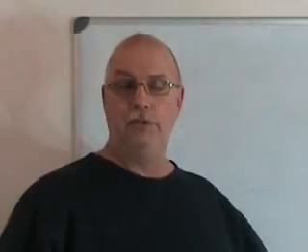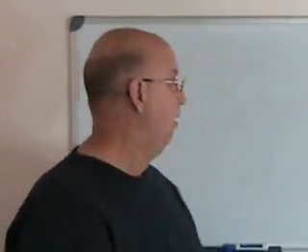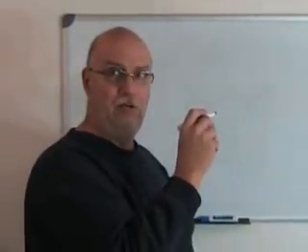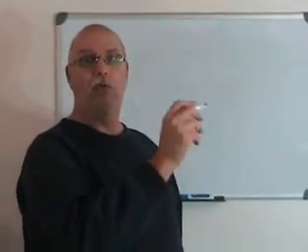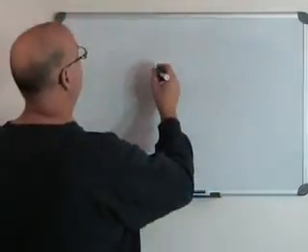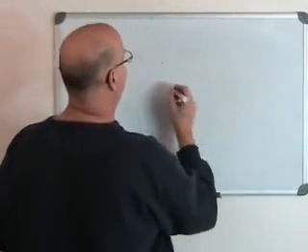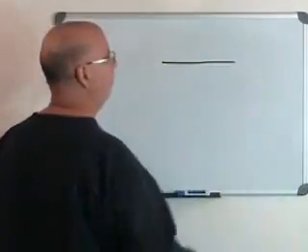Now, just before we get to our sketch, let's take a few seconds just to look at drawing lines themselves. Now, there's a lot of techniques, but a few little tricks that you can use that'll really help is one, to draw a straight line freehand. If you want to draw a straight line freehand, you're going to have to practice, and you're going to have to stop looking at the tip of your pencil. When you draw the line, place the pencil where you want it to start, and look at where you want it to end, and go there without looking at your pencil. So, take a look and see. At my start point, my finish point, I place, and I go.